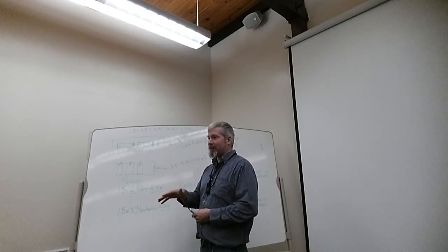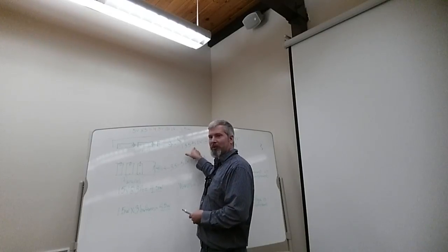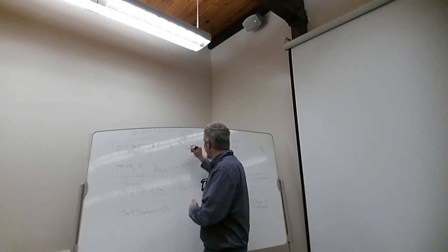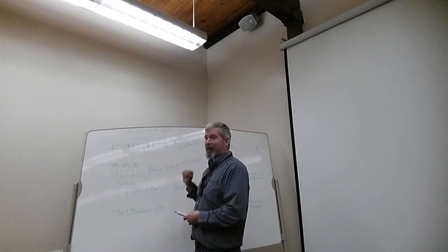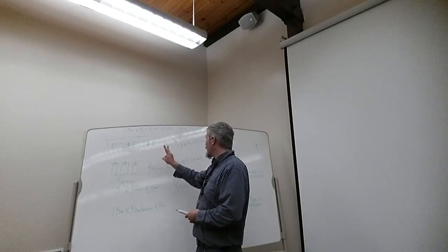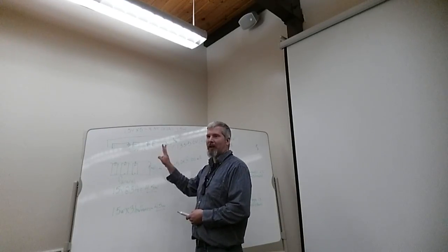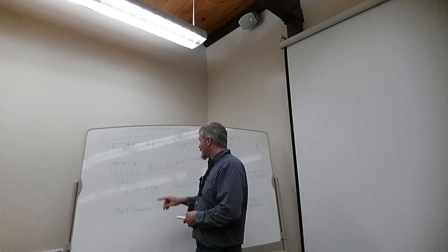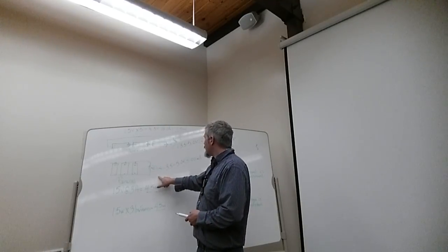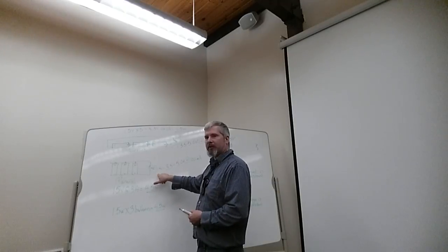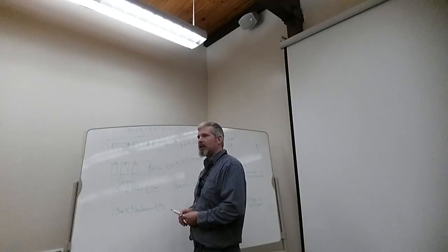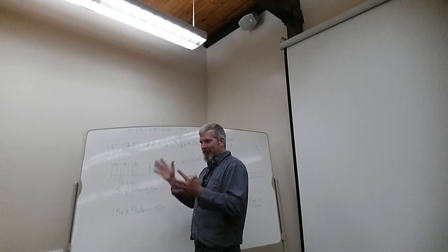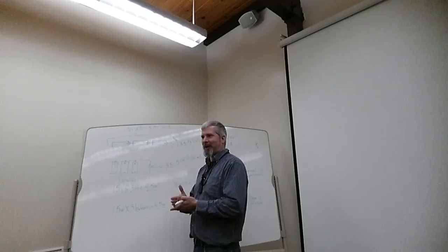Well, it has constant current, but it also is the operating voltage of the system, right? So the operating voltage of this light bulb is 3.5 to 5 volts. So we have to have it at 4.5 volts because it won't turn on. If I only had 2 batteries, that's not enough to turn it on. If I had 3 batteries, okay, now it can turn on. Now in this case, will this turn on? It won't turn on, right? Because we're at 1.5 volts. We're way, way below what it needs to be at. So that is the golden rule when you're trying to build a circuit. You need to build the voltage to operate the device.